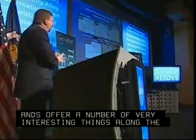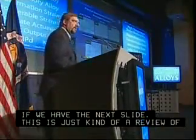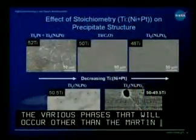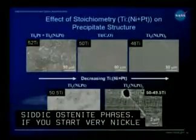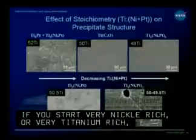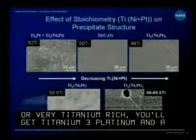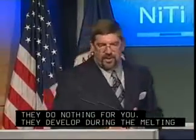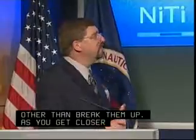This is just kind of a review of the various phases that will occur other than the martensitic and austenite phases in the titanium nickel platinum system. If you start very titanium rich, you'll get Ti3Pt and basically a Ti2Ni phase. Those are bad phases. They do absolutely nothing for you. They form interdendritically during the melting process. You can't dissolve them. You can't do anything with them other than break them up. As you get closer to stoichiometry, you lose the Ti3Pt phase, but you still have Ti2Ni phase.